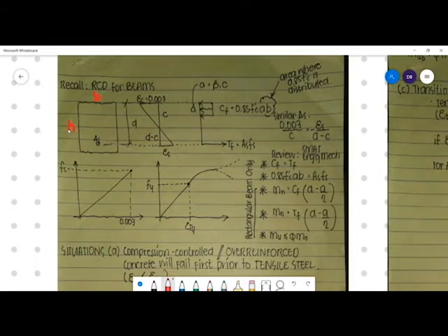concrete is weak in tension, because from your strength of materials, bending moment causes both tension and compression at a certain section and at a certain point in the beam. So we have what we call the compression fiber and the tension fiber.